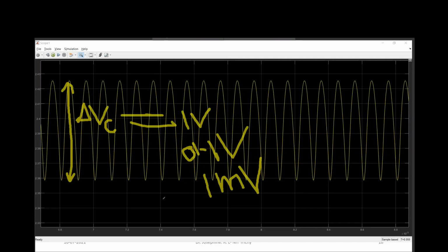But what some people do, if your network is large and you are using a microcontroller, the microcontroller will have some clock frequency. If you are operating at very high frequencies and you have multiple PWM networks from that, then it cannot generate that high frequency with multiple networks, because you're going to deploy the program using C language. C language is sequential. As it is sequential, the entire clock frequency is going to split among them. For that, you have to compromise in switching frequency and go for a higher capacitance value.